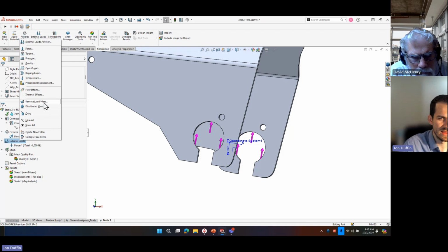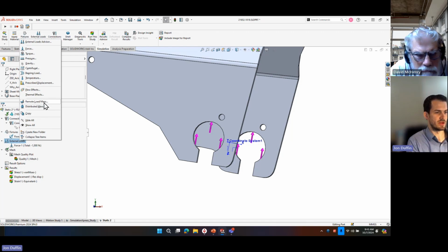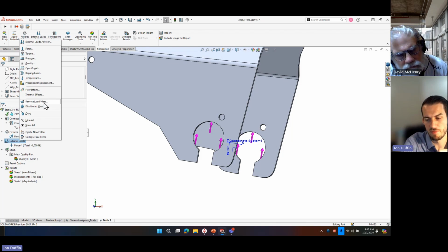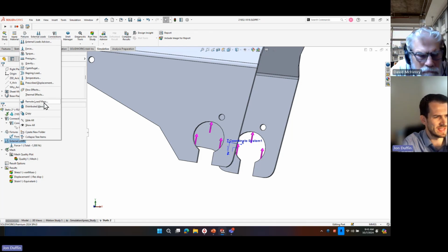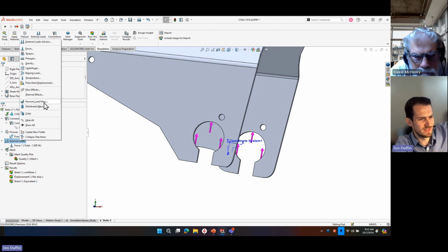What that does is apply the loading at a certain distance away. So this is how you would set it up if the loading is on the axle in the middle and distributed over those faces, or with your setup from before with the pedals, where I know I have a force on these pedals that's transferring the load directly into here.